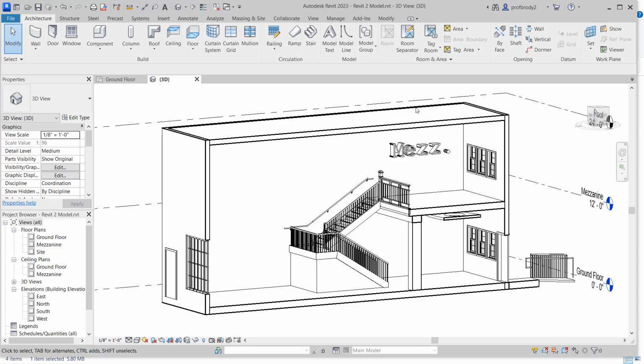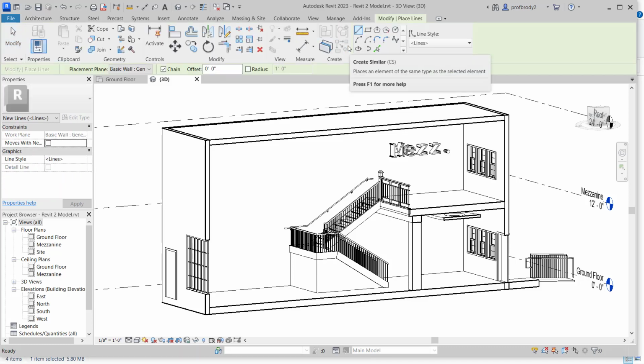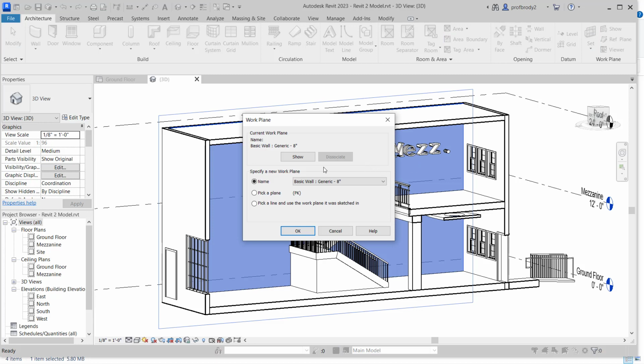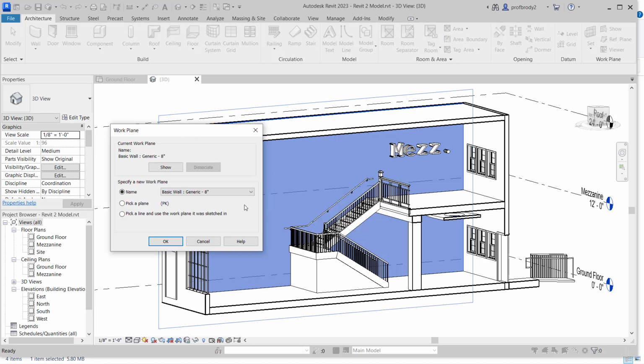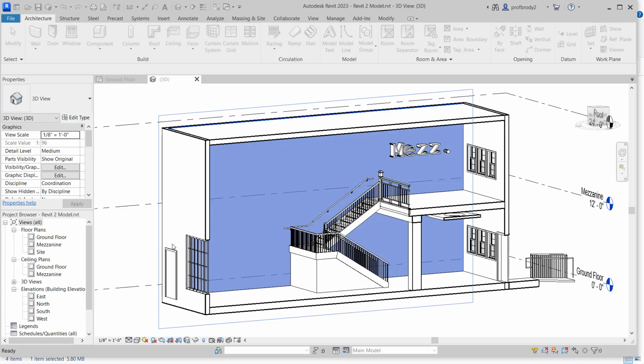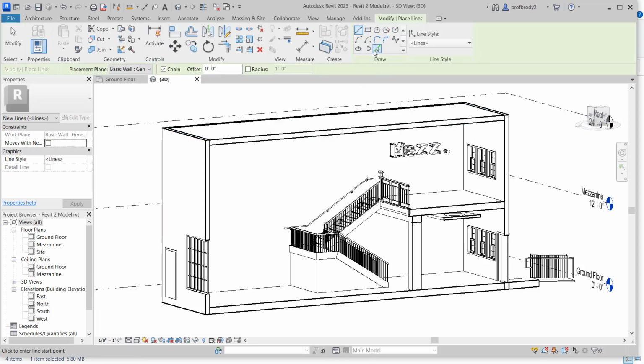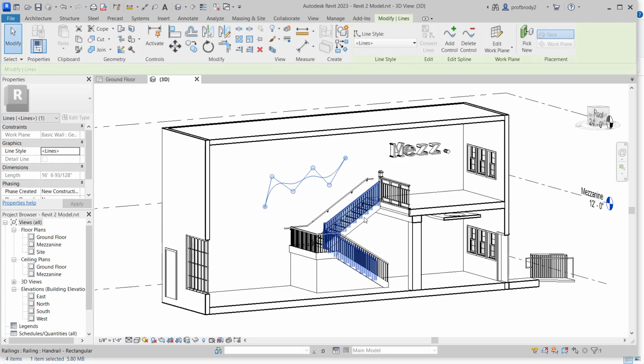Really fun. The other thing you can do is draw using model lines. We don't do this a whole lot, but it works in a very similar way. You'll want to define the surface that you want to draw on first. It remembers that that's where we were drawing from last time. And OK. And now with your model lines, you can just come in and draw whatever sort of thing you want. These aren't great because they unfortunately don't render particularly well, so we tend not to use the model lines all that much.